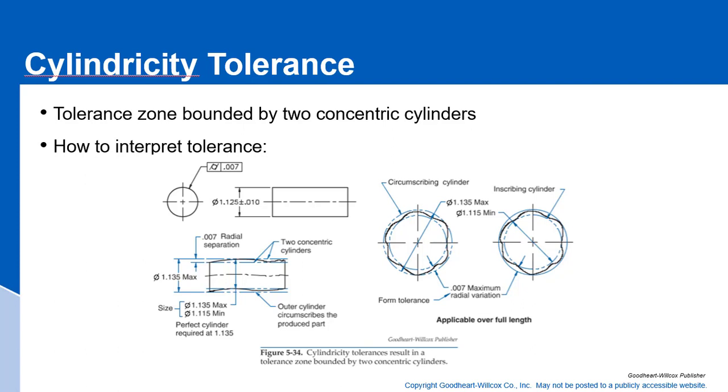And then it's like the difference between circularity, which covers just one circular element in your part, whereas cylindricity covers all of the circular elements considered all together. In which case, cylindricity is to circularity kind of like what flatness is to straightness. So there's a little bit of analogy there between straightness and flatness, and between circularity and cylindricity. And this is how you interpret that.